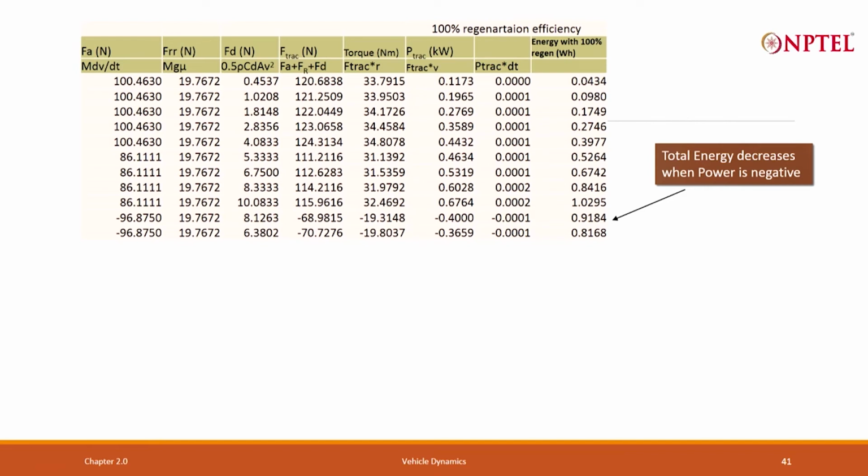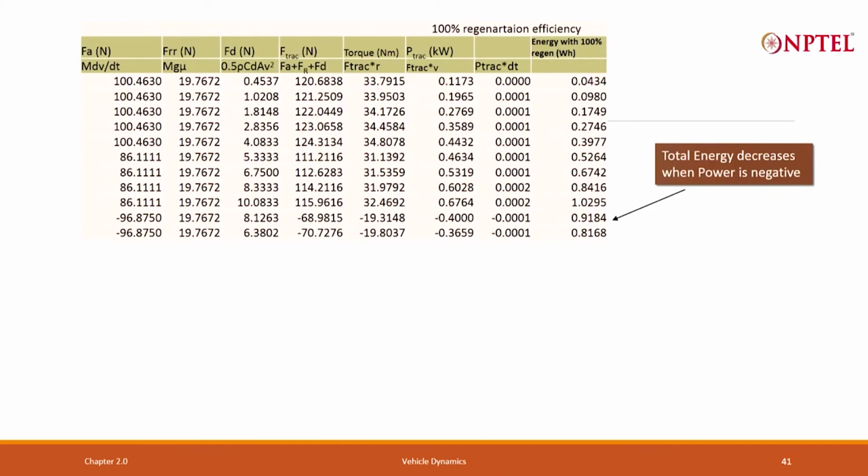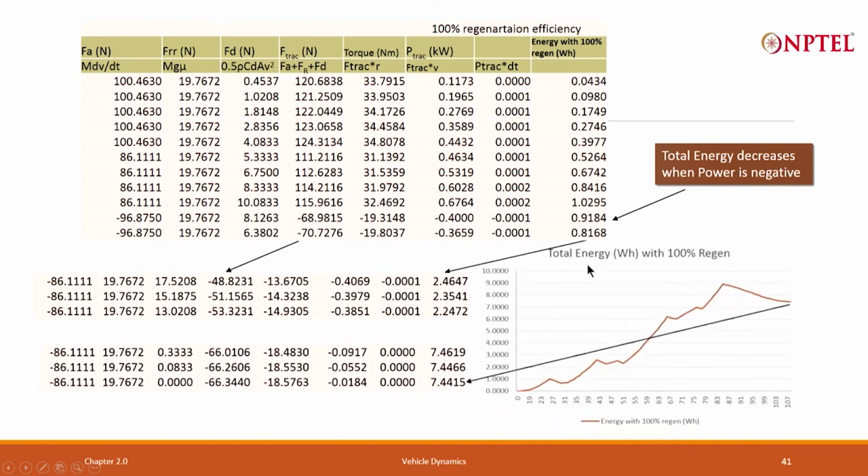I can also find out the distance that I travelled, which I did in the previous step, and from these two I can compute the watt hour per kilometer. I am showing the same thing on this side, this energy comes here. I have taken this part of the data and then I also take the data more. And if I see this, I am plotting for the whole, I do not have 108 rows here, I am only showing a limited number of rows, but I am actually plotting for all of the 108.